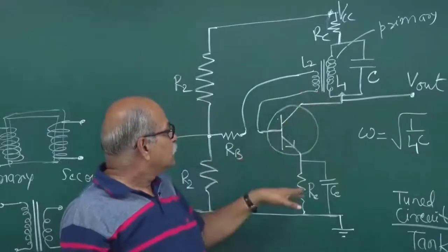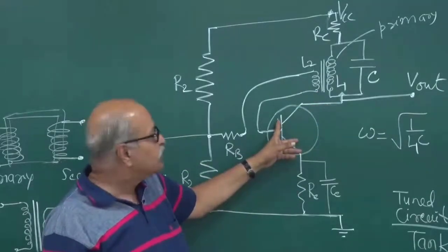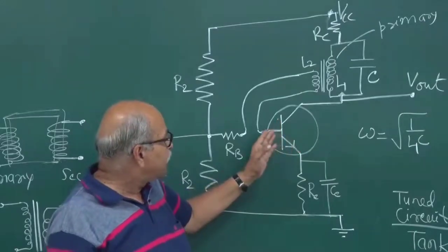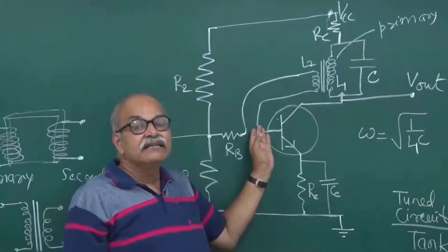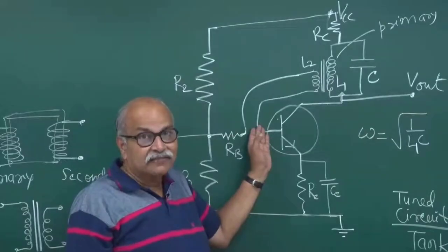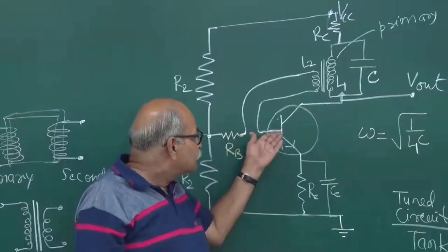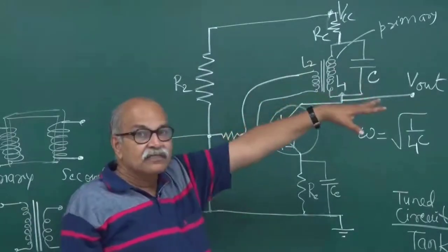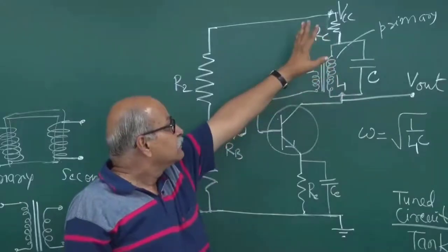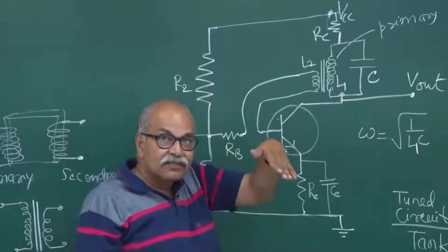So in that common emitter mode, when you do amplification, the phase of the output signal and the input signal differ by pi, right? Because if this base biasing voltage increases and current increases, then on the other side the current in the collector circuit increases, and then the output voltage goes down.